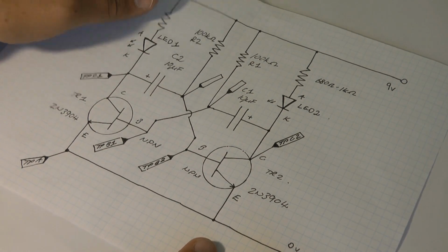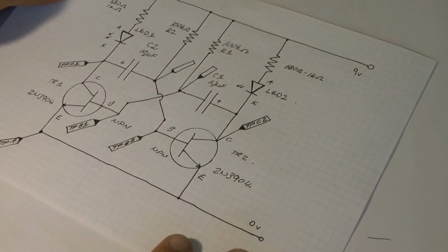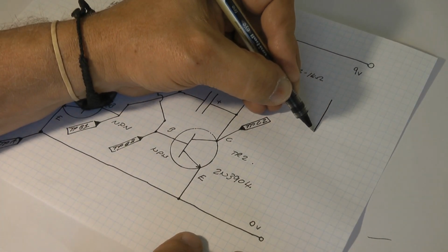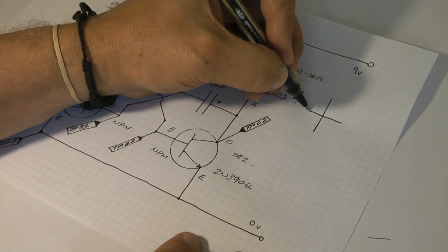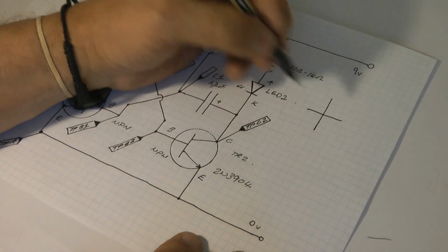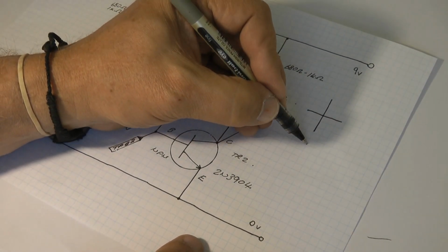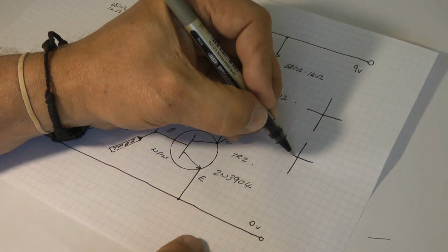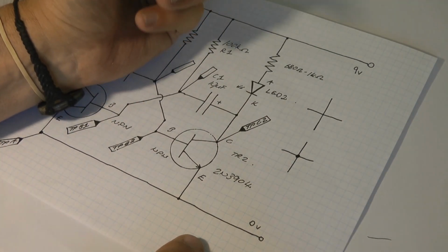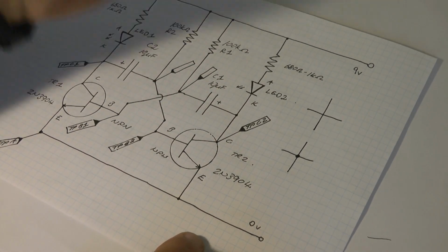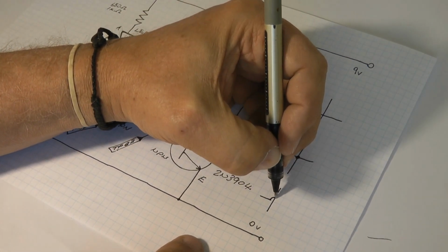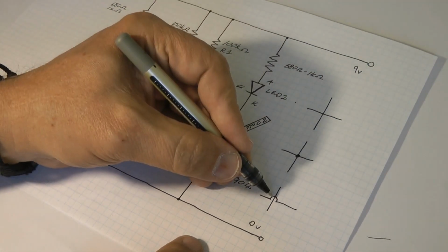So let's just clarify one thing for those of you who are relatively new to electronics. If you're looking at a circuit diagram and you see a crossing like that, that is not connected. And I'll explain that in a moment. But if you see this, then you definitely have a connection. That means connected, not connected. What I normally do to help my students understand better is if this is a wire going this way and it's not connected, I'll do a jump over like that.